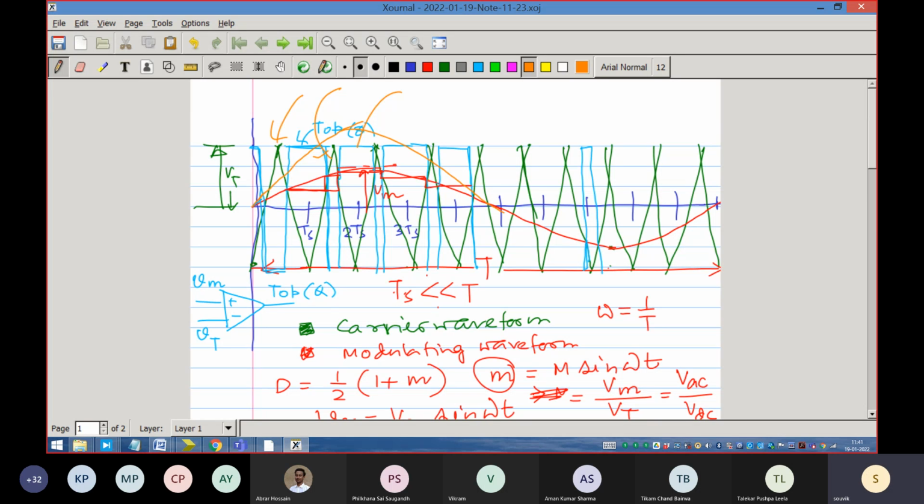High frequency harmonics we are always tolerating. They are not a problem, because they are filtered by the leakage inductance of the machine, since at high frequency the leakage inductance presents a higher impedance, giving better attenuation. But the low frequency harmonics will come across the machine terminal, and with them the induction machine torque-speed characteristics will be very much affected. It will produce pulsating torque. It will have a lot of issues. It will have a lot of unnecessary current in the machine. The machine will be heated and all sorts of things.